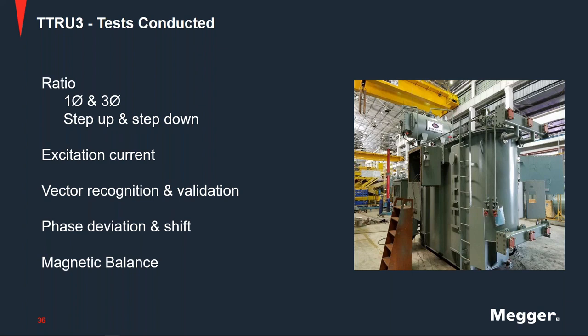So if you excite phase A, it will look at the ratio of induced voltage on phase B and phase C. It's typically used in India during transformer construction to look for any problems when they're winding the core or putting the winding on the core. But it can also be used to validate the state of magnetization within the transformer, which is where we would expect most people to find value in that software feature.